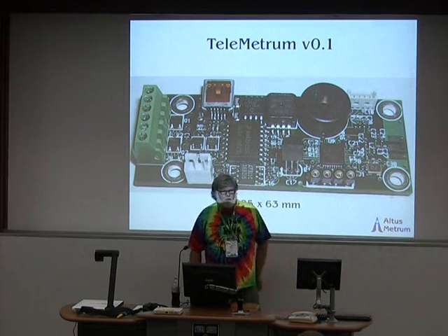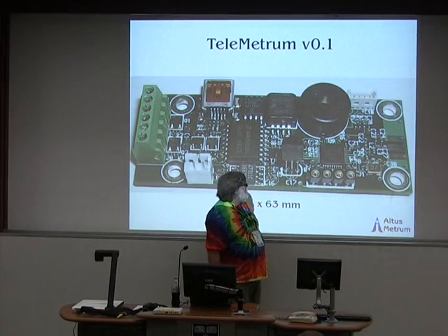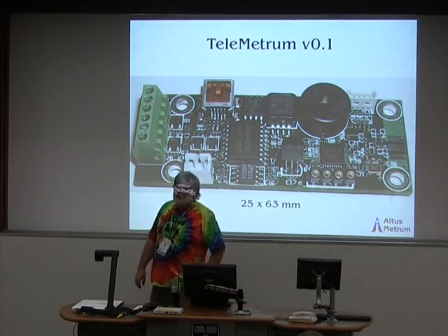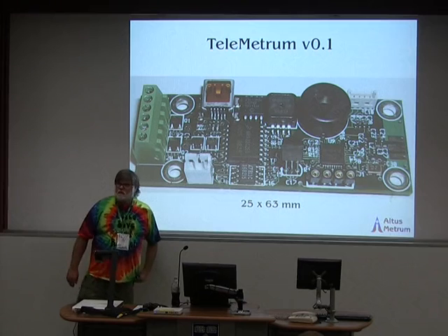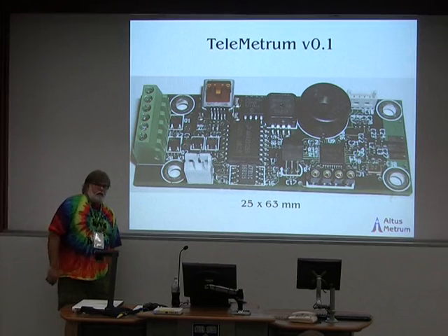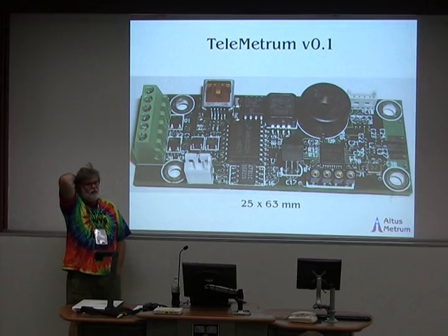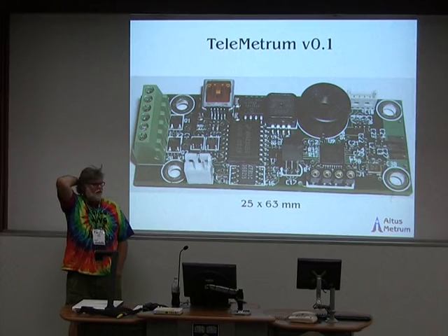So we have a quarter wave whip on the transmitting side. The radio puts out 10 milliwatts or plus 10 dBm. Doesn't sound like very much, does it? I forget what the numbers are, but with our current modulation and coding scheme, the theoretical range ought to be on the order of 30 kilometers in free space or something like that.